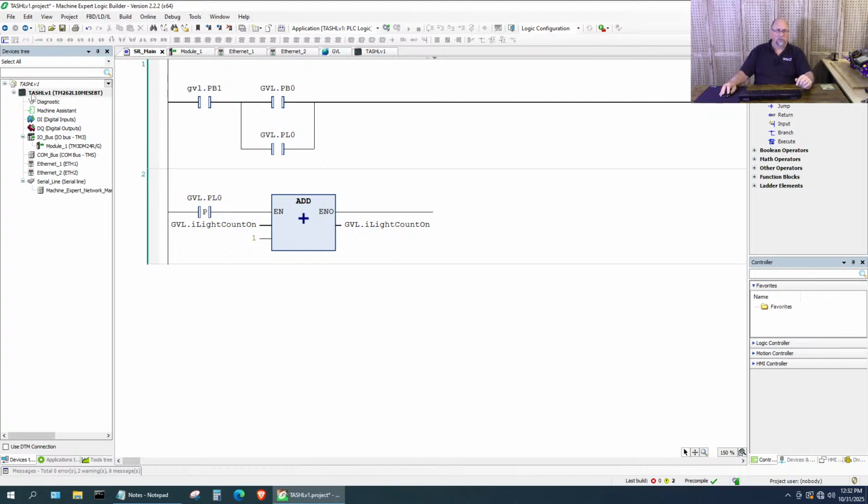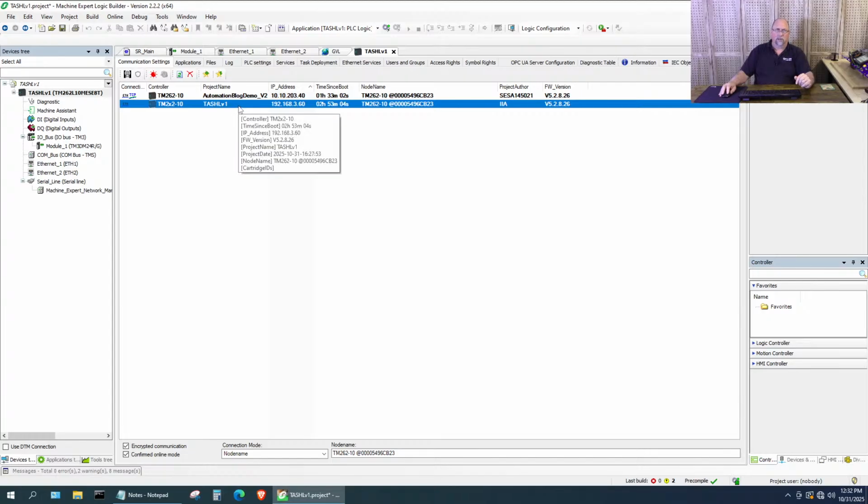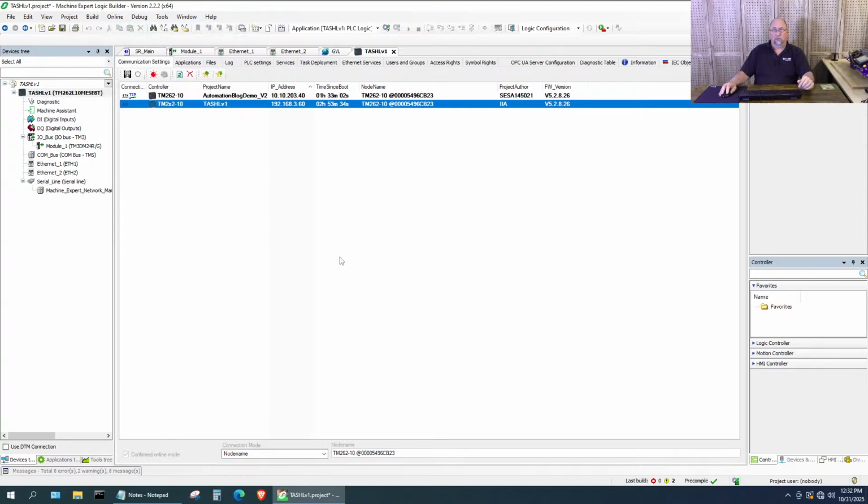But in any case, I think the one thing I did when I went to go online is you want to double click on your controller, right? Or your PLC, whatever we're calling it today. And then double click on the device to select it, right? And maybe you don't have to, maybe you can just single click it, but then I can go online, log in, and away we go.